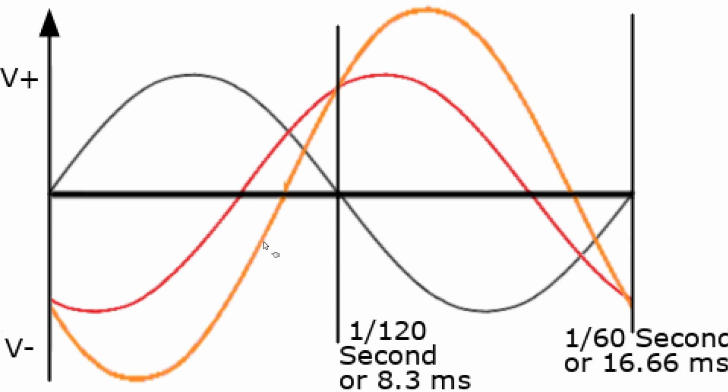And the orange line would represent the voltage difference between the two wires. So as you can see, the greatest voltage difference is right in here, where that one's leaving its hump and that one's approaching its hump. And there's zero voltage difference here, where these two lines cross. And then again, there's greatest voltage right up in here, where this one's just leaving its hump and this one's just approaching its hump. Again, there's zero voltage difference here, where those two lines cross.